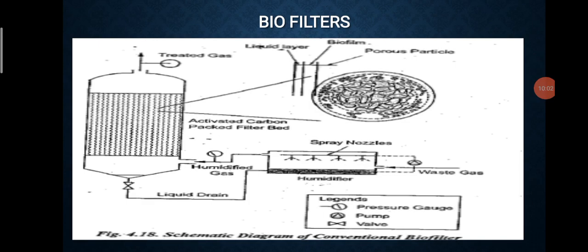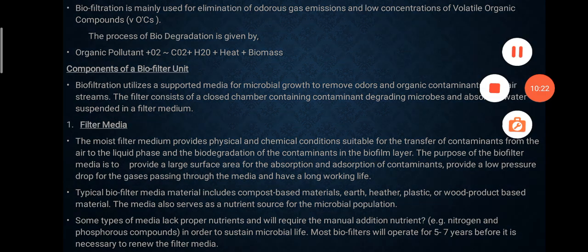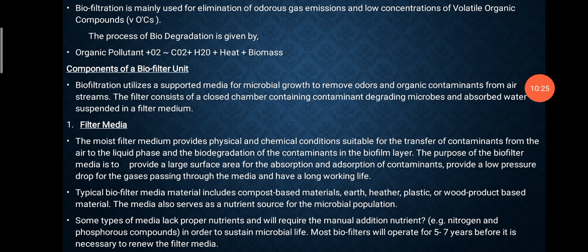Biofilters. Biofiltration is mainly used for elimination of odors of gases and low concentration of volatile organic compounds. The process of biodegradation is given by organic pollutant plus O2 gives CO2 plus H2O plus heat plus biomass.